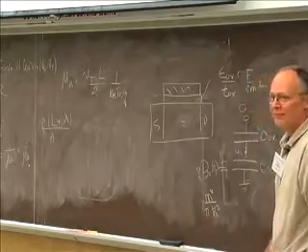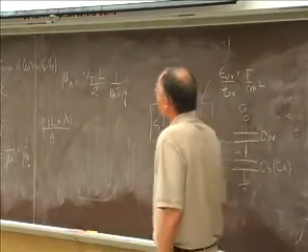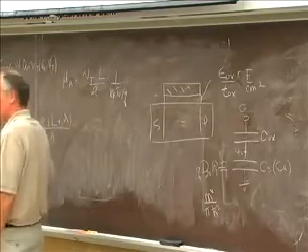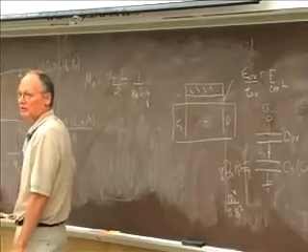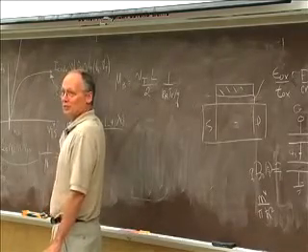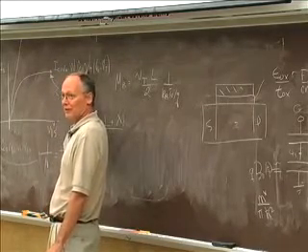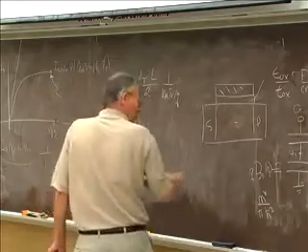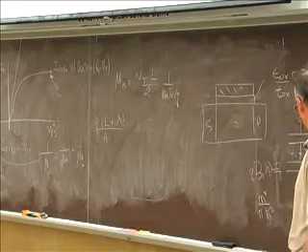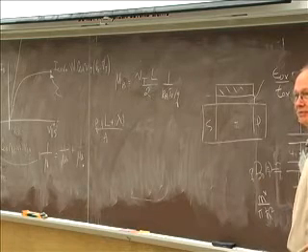Right? So in III-Vs, the light effective mass that's giving you the high mobility might not be so important because your ballistic mobility is going to limit you, but it's also giving you the high thermal velocity, which is important because it gives you a higher drive current, which you want. It's also giving you a lower density of states capacitance here.